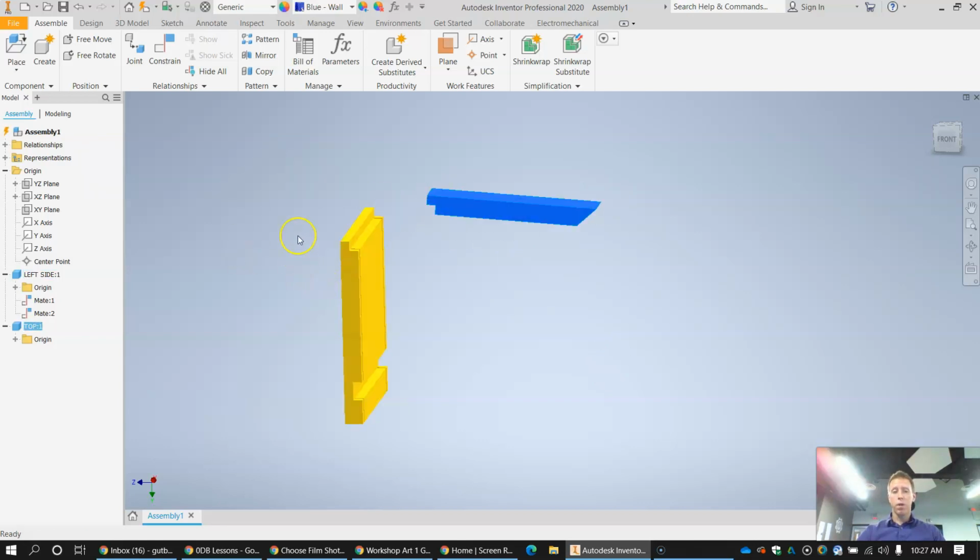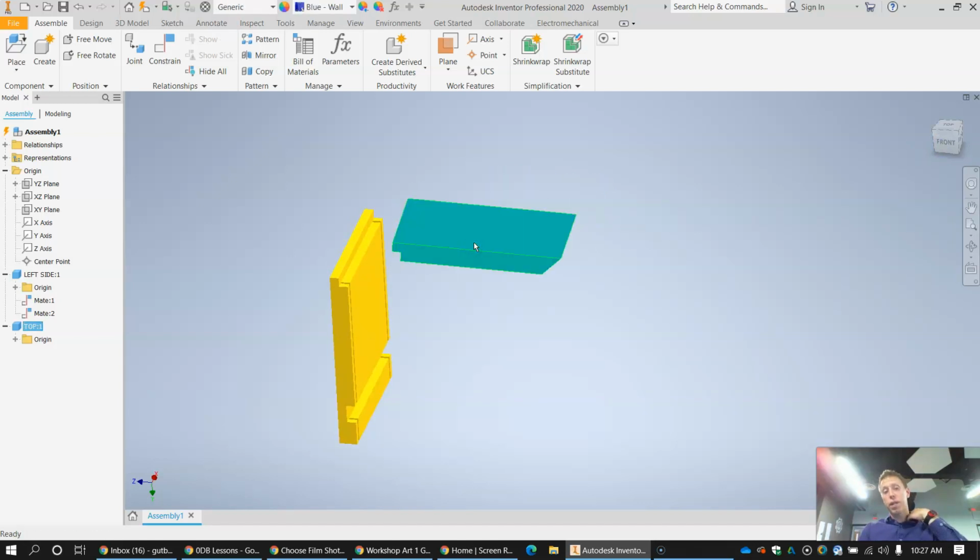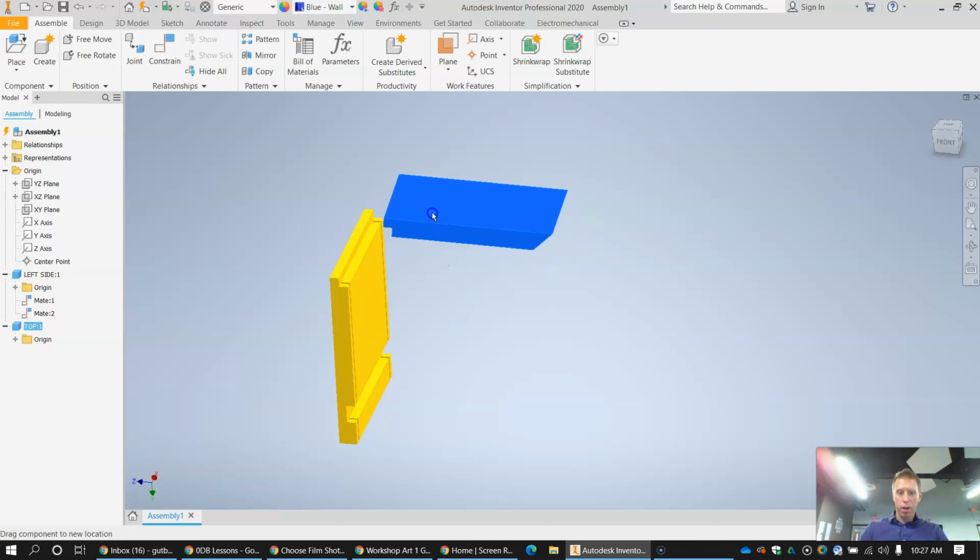With assembling, essentially what you're doing in this 3D world, you're telling the relationship. What's the relationship between those two pieces? So in this case, I'm essentially telling the pieces to go kind of like this. I don't have the right joint at the top, but I'm kind of telling the pieces to go like this. In the bottom left corner, you see we have 3 axes. So in general, most of the time when you're constraining, you have to do 3 constraints, 1 in each axis to keep the thing from moving in the other axes.